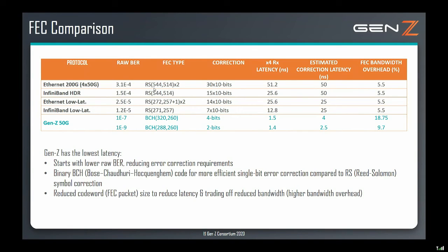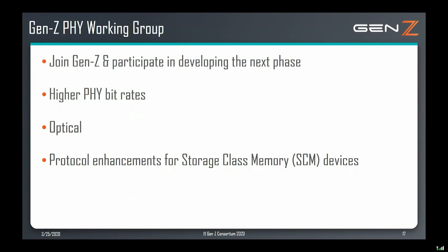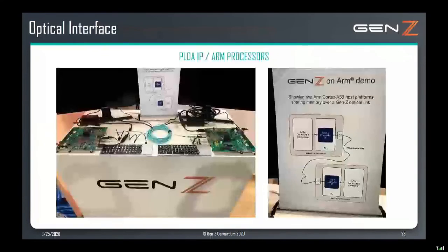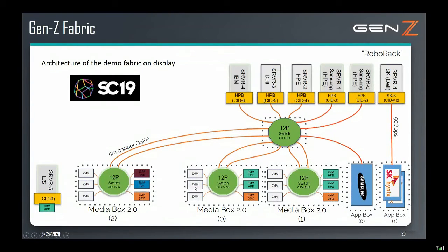Okay. There was a question, I believe it was in reference to some of the demo images that you were showing. I can't be certain. But the question is, on the 12P, is this 48 lanes total or 96 lanes? Okay, let me just jump to that. So 12 ports, and each of these ports are 4 lanes wide, so it's going to be 48. I think the question is about whether it's bidirectional as well. Gen-Z has bidirectional PHYs, so these, I believe, are 48 lane switches.